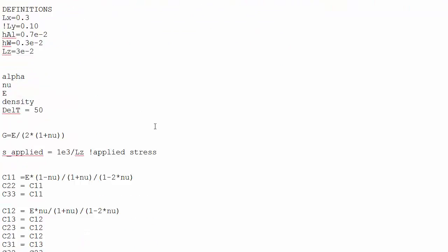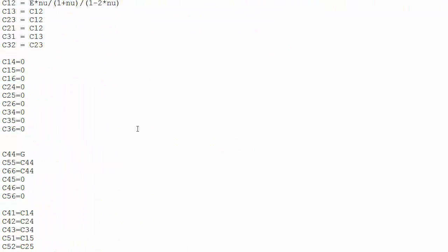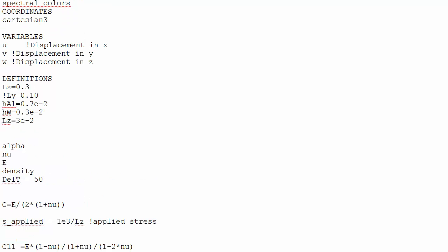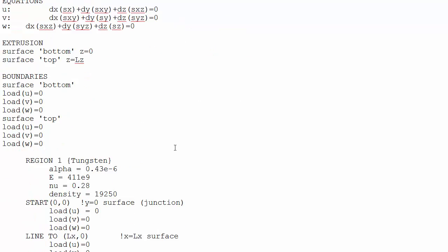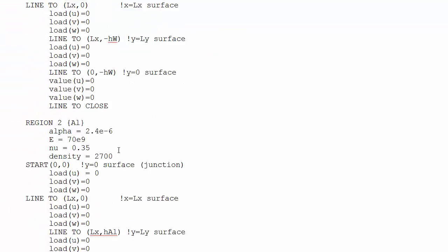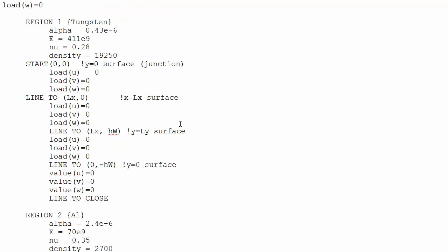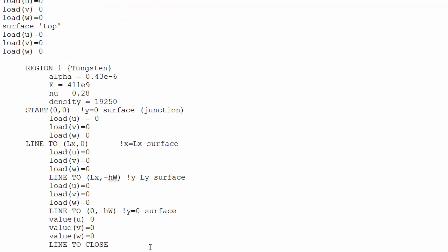So how this works is you are going to set up different values for these parameters in different layers. So first you declare them in the definition section so that you can use them in your equations here, but you don't actually set values for them. Instead, you set those values in the different regions. So this is a bit simpler of a region definition problem than the one that we did back in the start of thermal expansion, where we had the two rods kind of hitting each other.